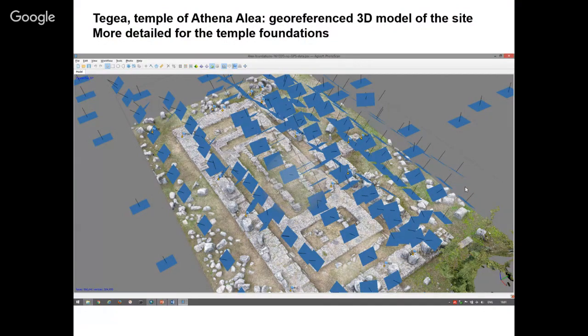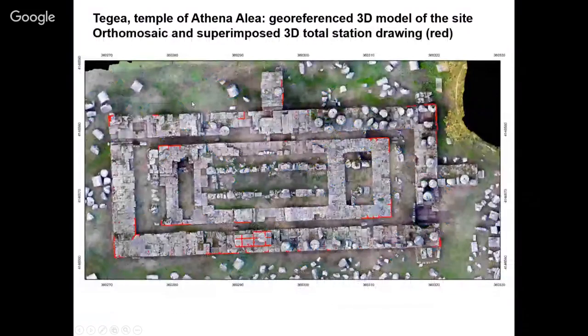So we brushed all of the foundations clean, and then I ran the drone. In between we documented precisely the size of the foundations and where they lie, also with the stations, and that was done in about half a day's work or even less. That's just getting enough documentation of the size of the foundation.